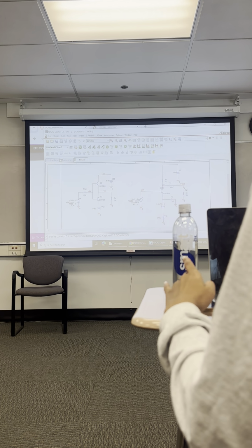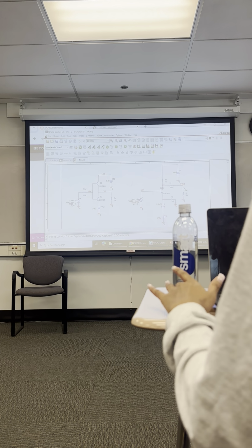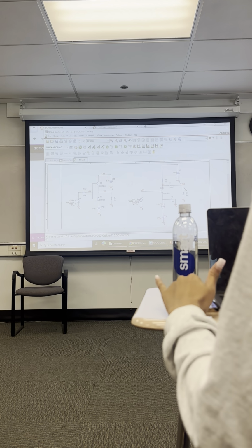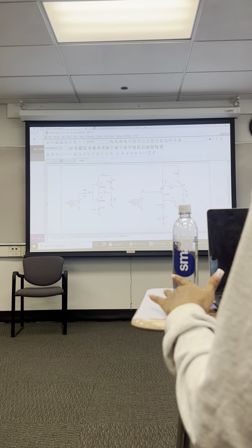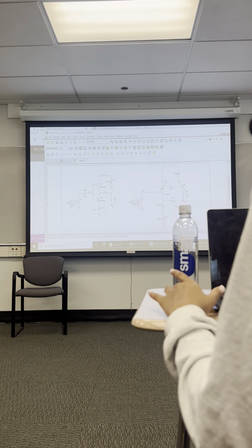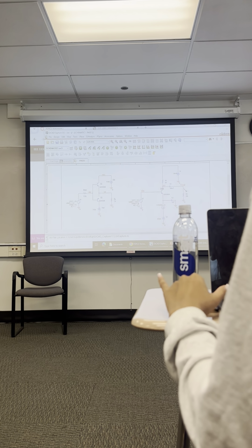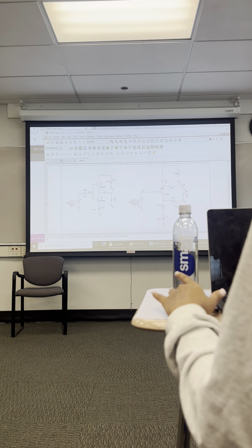We put a Vout in the circuit, and there's a Vin. The input is small signal, 10 millivolts amplitude, and you just decide on your own input frequency. You can use 10 kilohertz, 15 kilohertz, 5 kilohertz, 3 kilohertz. Here it's just using one kilohertz. So this schematic is going to check your paper design compared to your simulation results.